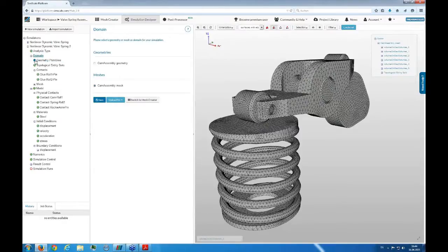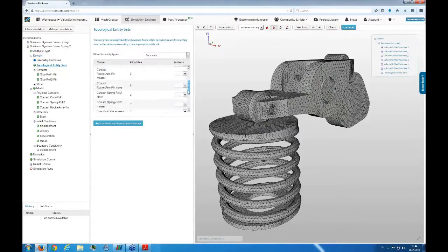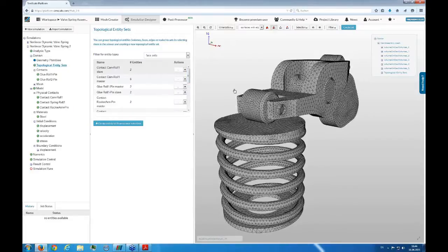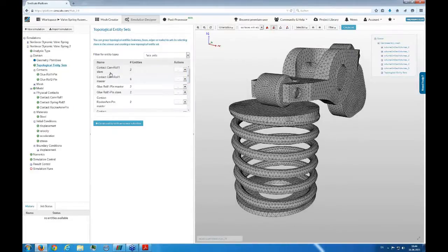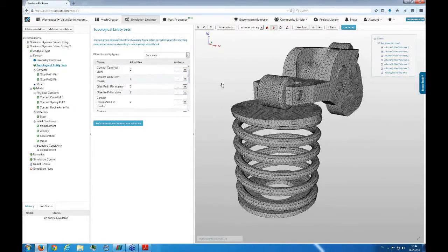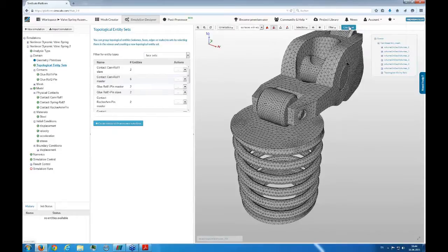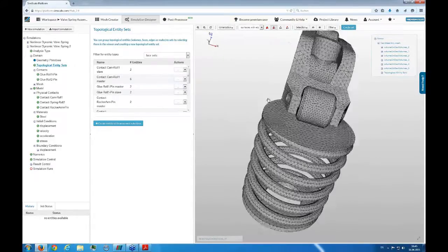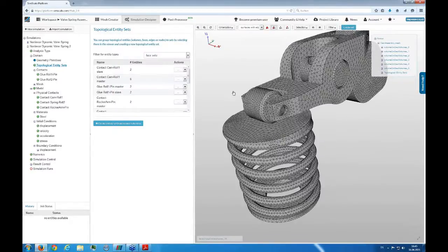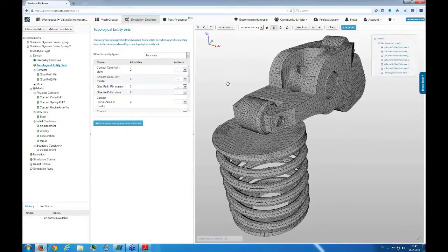Okay, then what we first set up in almost any simulation we do are the different sets we have to use later. Normally, for any boundary condition or load, as you already know, you can use either the faces or volumes directly, or you can beforehand create sets of the significant faces, which will ease the later assignment of boundary conditions. So we created some sets already.